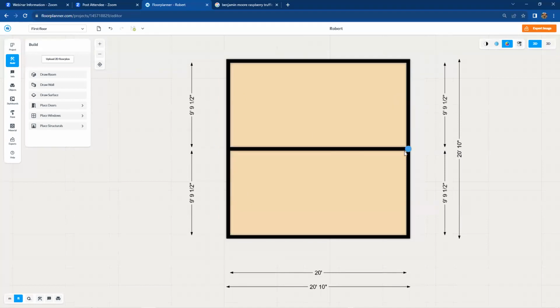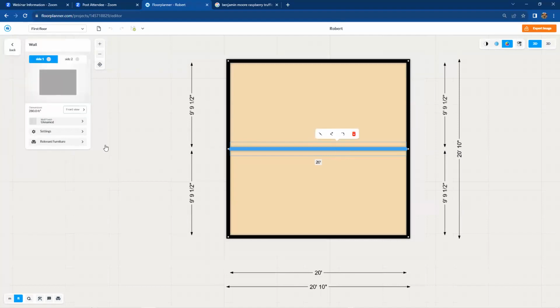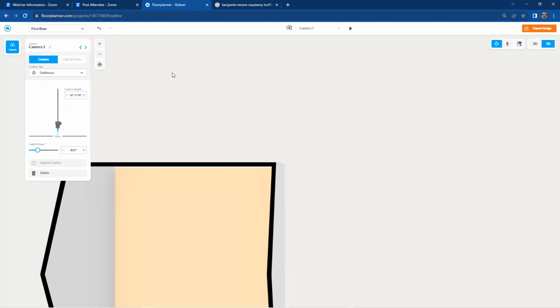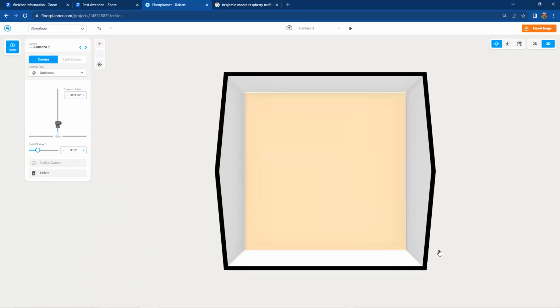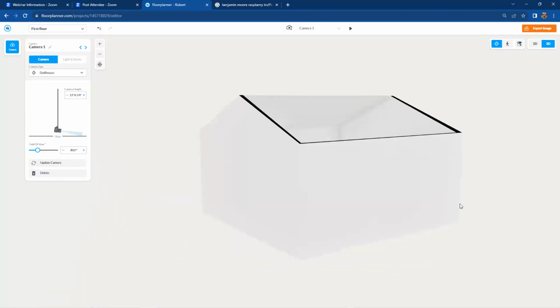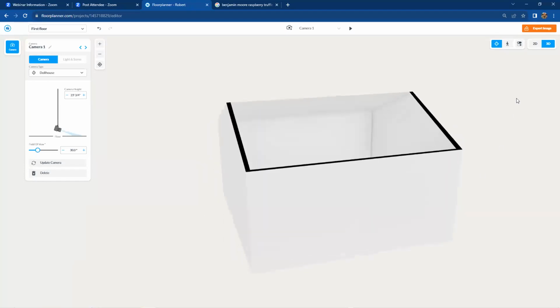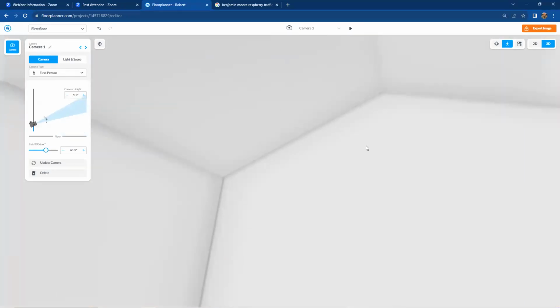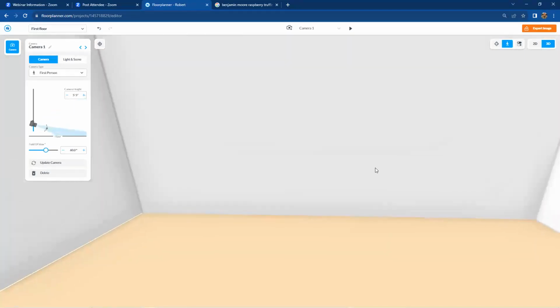With this being constructed, we fixed our ceiling, but I did not want a wall in the middle of my room. So I can select the wall, as we talked about earlier, go to its settings and give it a 0 thickness. That's invisible. And go to 3D and zoom extents, see what we built. And it's perfect, looking great. And if I go inside the room with my interior first person, looking up, looking down, it all looks great,